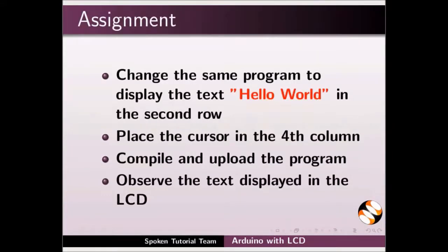Do the following assignment. Change the same program to display the text Hello World in the second row. Place the cursor in the fourth column. Compile and upload the program. Observe the text displayed in the LCD.